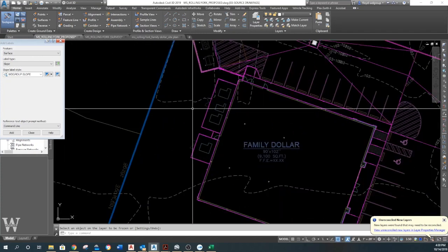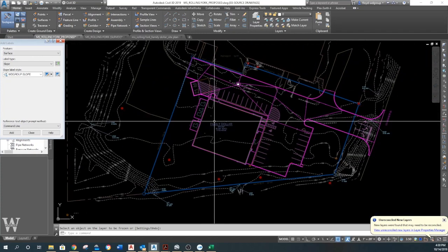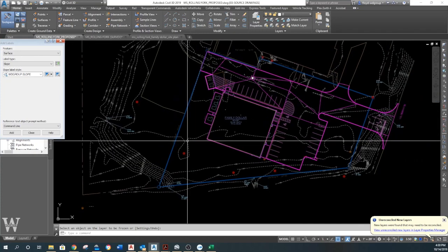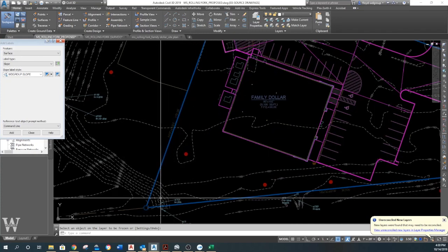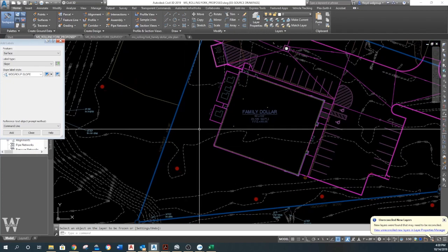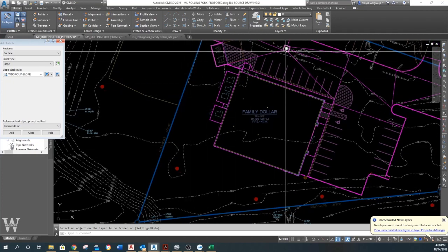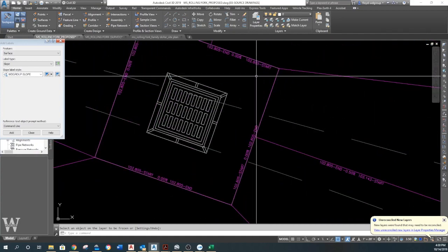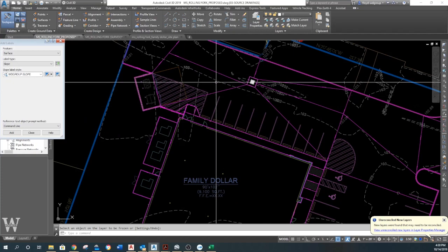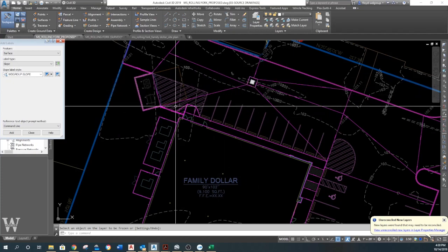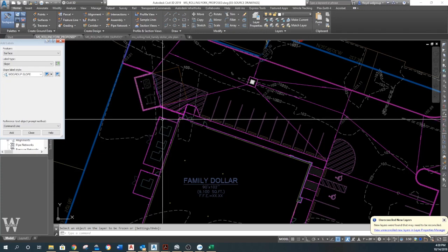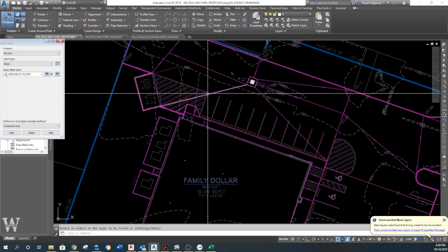All right, now I'm ready to put my pond in. So I'm going to put one in the back, and I'm going to just discharge it right here. Okay, so I really kind of want a long, skinny pond. If the top of that's 102.82, it doesn't need a lot of pipe out of here. 12-inch pipe is plenty big to get that water out of there. And how do I know that? Because I've been doing this for a long time, and I know 12-inch pipe, if I calculate it, was more than enough for that little area of water.